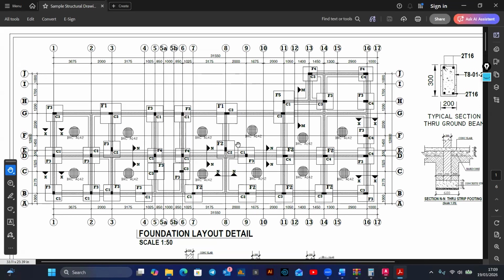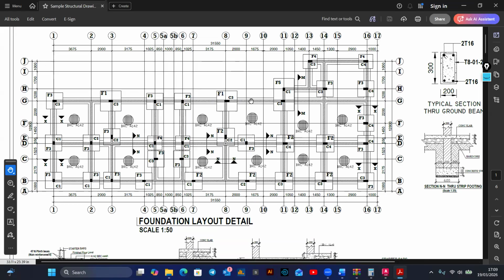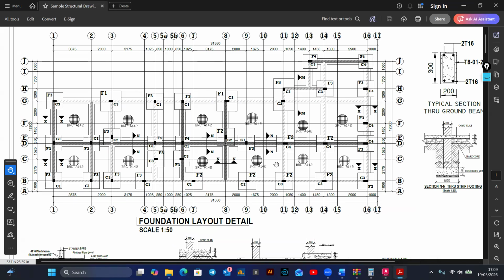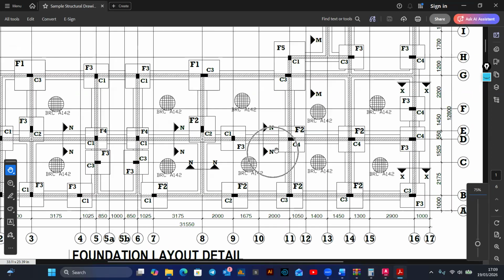So now you'll be required to at least add some form of hatching to show where the beams are going to pass and also the extent of the foundation strip. That is the only way you can differentiate them. You need to put some kind of hatching.